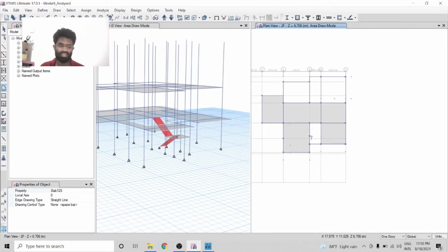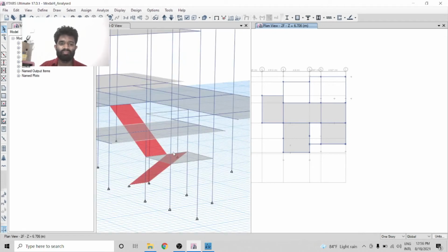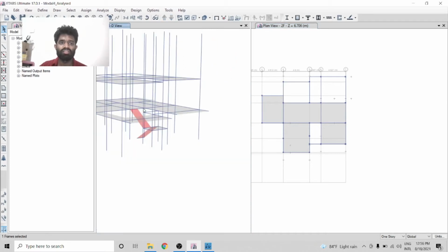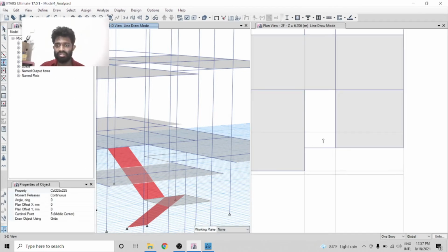Here I have the staircase, which is used from first floor to roof terrace. So I have to take a look at that. As previously we did something like this, not this one. Here I haven't a column, so I have to draw a dummy column here. Otherwise I can't manage with the landing level, so I have to use a dummy column here. To draw a column.